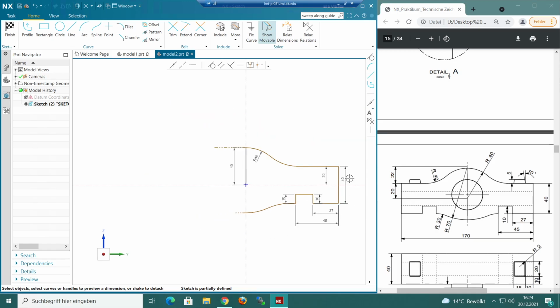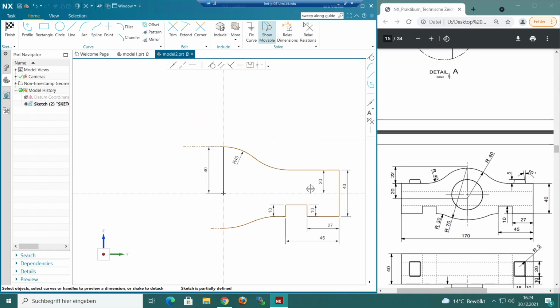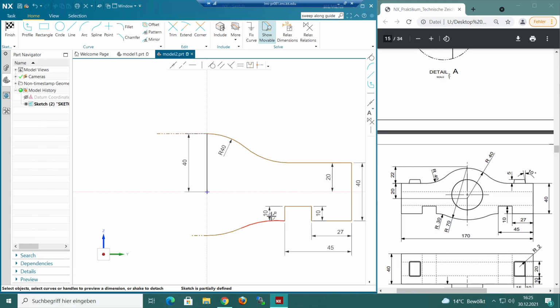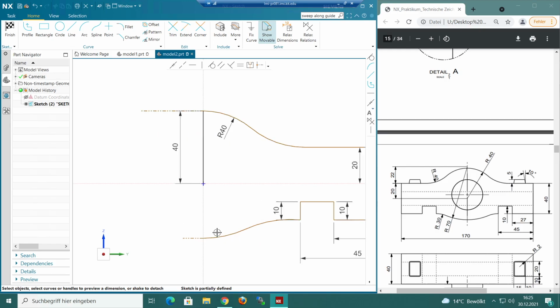And now you see we more and more get to the shape that we want. But it's not as straightforward as before, and that's why I'm showing you this part, because you have to do some thinking, like with these tangents and everything. So still, you see it's not defined completely, and that's because we also need to do the radiuses of these right here, and you can see it's 40. So if it's 40 here and the thing is mirrored, so to say, then that will be 40. Okay, so we need to do a radius of 40 right here.